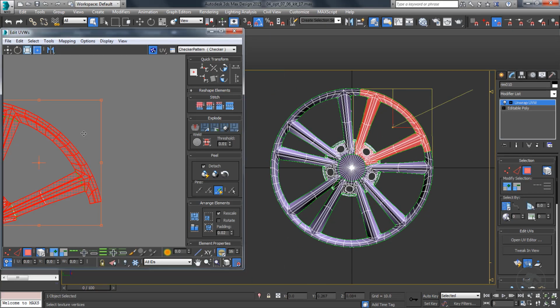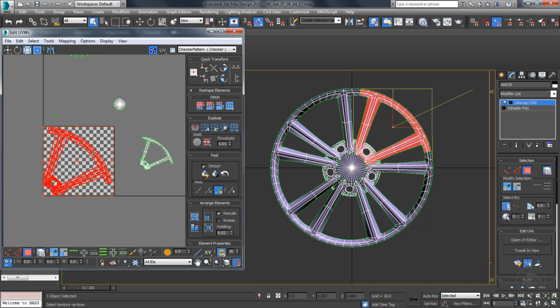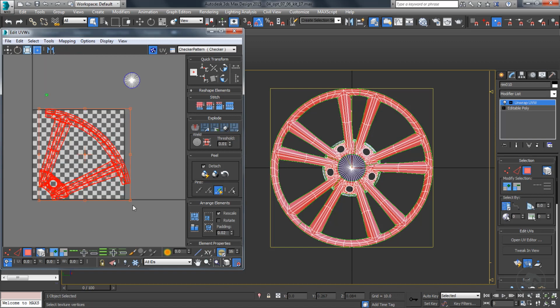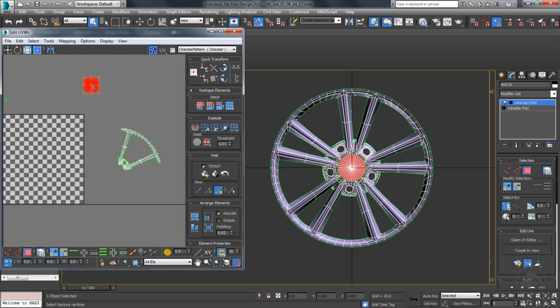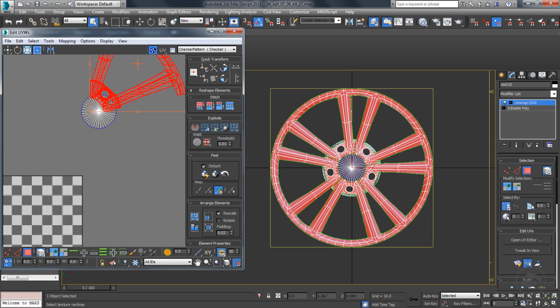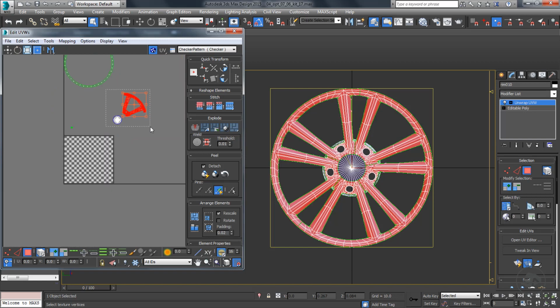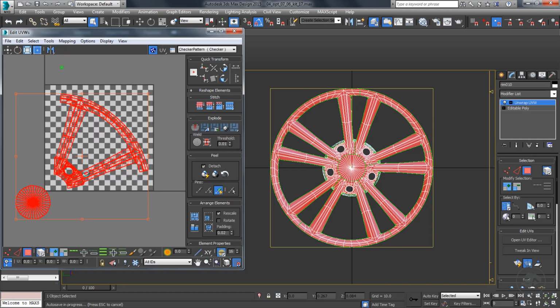After completing the alignment, move and scale one of the pillar pair UVs to match the checker box. It's better to scale all pillars' UVs together with the emblem UVs for precision and to save time later when we create the final UV map. Use unified scale while scaling the UVs.